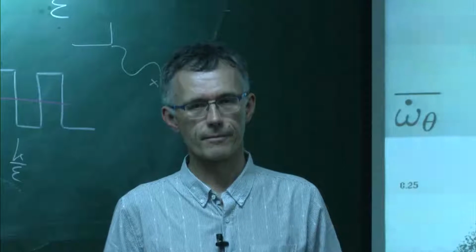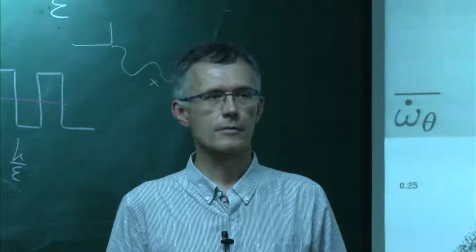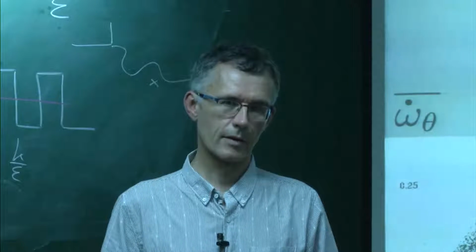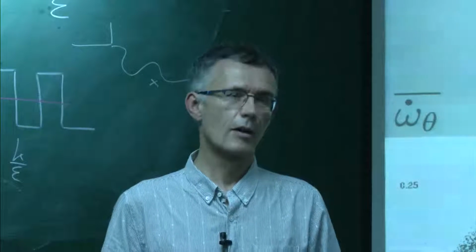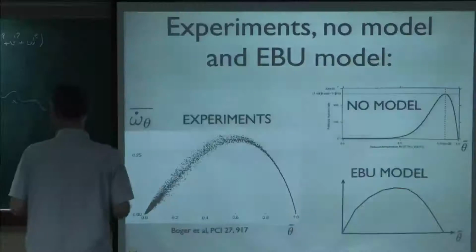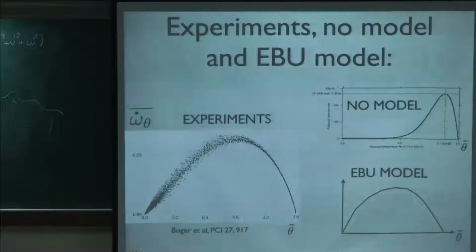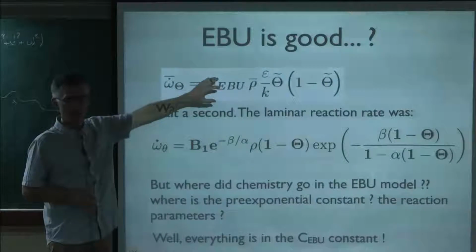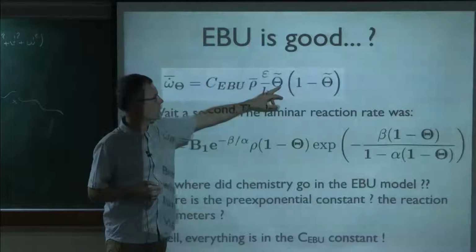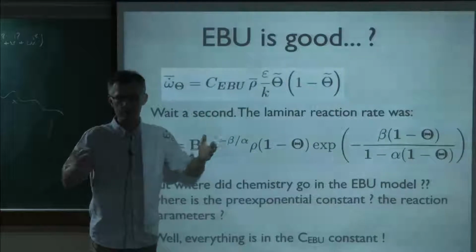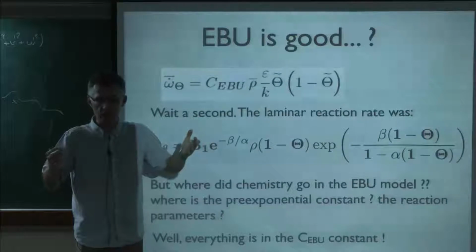Wherever there is air and fuel mixing, ignition happens. But in the EDC concept, the eddy dissipation concept, no matter how rich or how fuel-lean a mixture I give, it doesn't ignite. Well, that's another problem. But it's true that if you talk about ignition in a model like this, it's complicated, okay? If you use this expression, and at one point you set theta to 0.1, then it starts burning. And you cannot stop it because there's no chemistry.